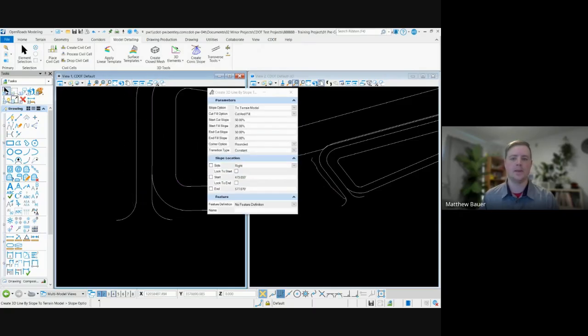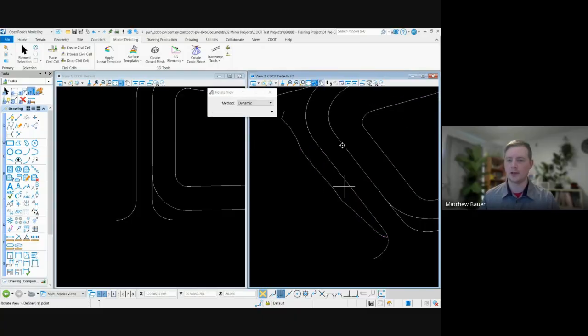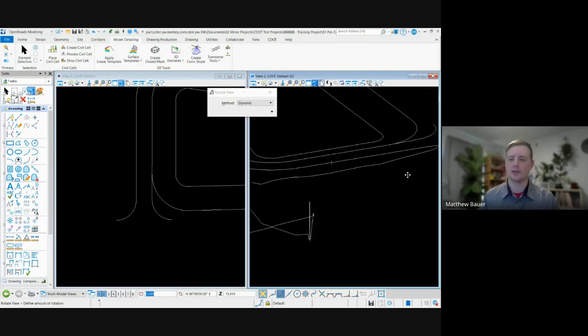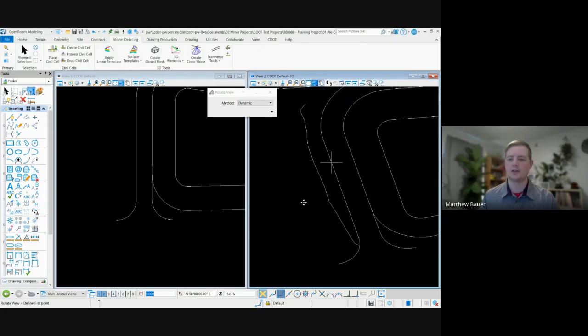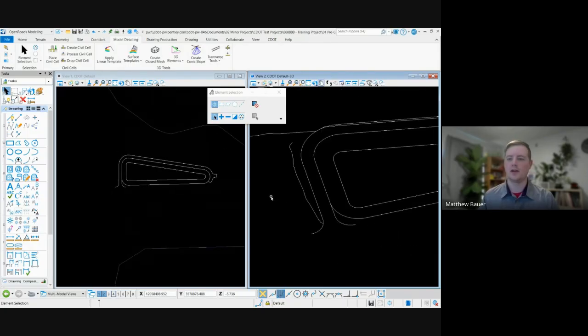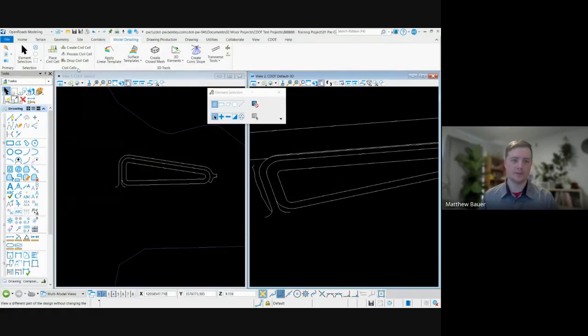And now, if you see over here, this has drawn a 3D feature line along where our slope will intercept the existing surface. So now I'm not trying to draw slopes. This can be done by linear templates, but I think this 3D elements tool is just as good to just throw something down there. So now we have our elements here. So now we actually need to make it into a surface.